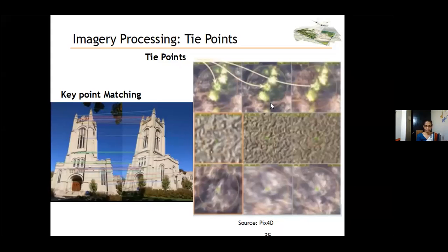There are various reasons why the same point may not appear in the other photograph. So if we can't obtain a matching point, that means this is a key point and not a tie point. Only matched points we consider as tie points. You can see a nice output here of the match points, based on any feature matching software we can use to get this result.